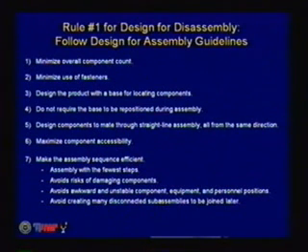The removal direction is generally orthogonal, or at least different from the snap fit direction. It can be impossible to do without destructive disassembly. It might be great for assembly but terrible for disassembly, unless you have a snap fit that can disassemble itself, and there's research going on right now here in mechanical engineering on that topic. So don't follow these guidelines blindly, but they do make sense from a disassembly standpoint too.